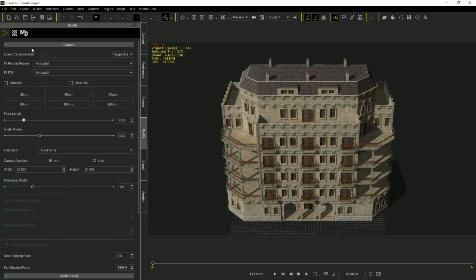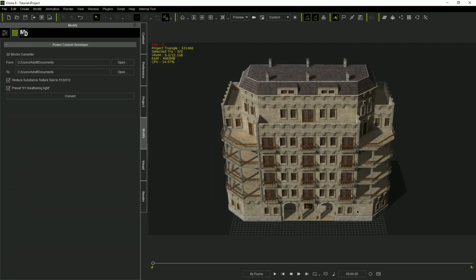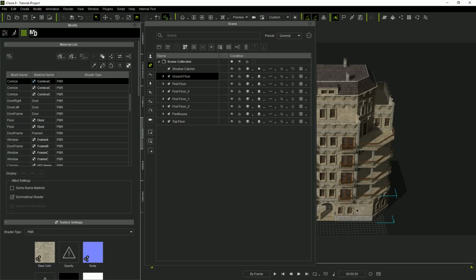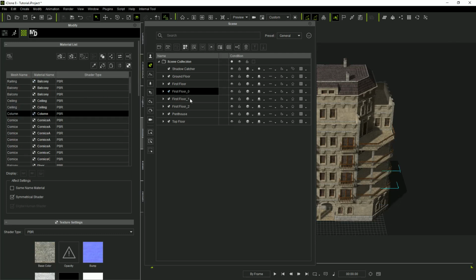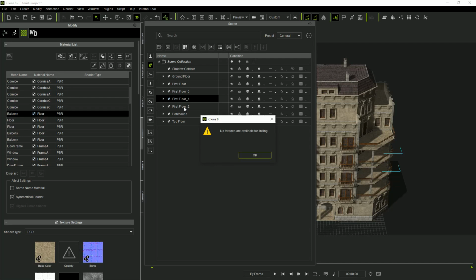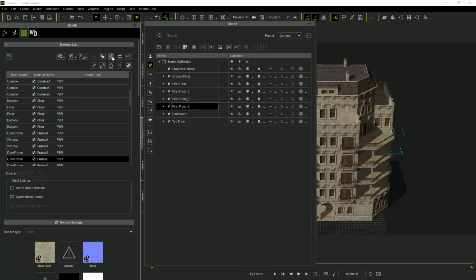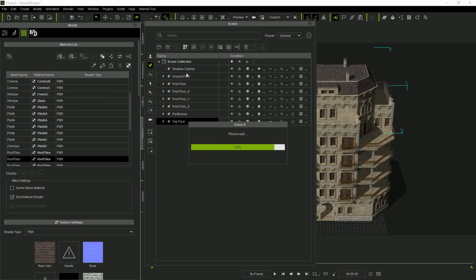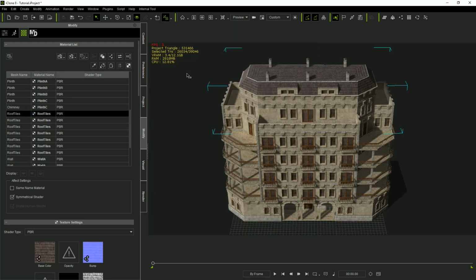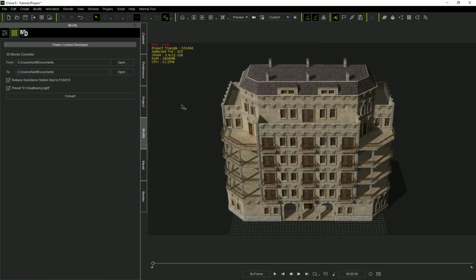After opening the Material Editor in the Modify panel, now we do the same link material operation we did for the ground floor, for each one of the floors of the building. Notice that the duplicated floors already get their materials linked, and we get messages indicating that no further material linking is available in those floors. Once we have done this operation, we can see that the graphic memory has been drastically reduced again.